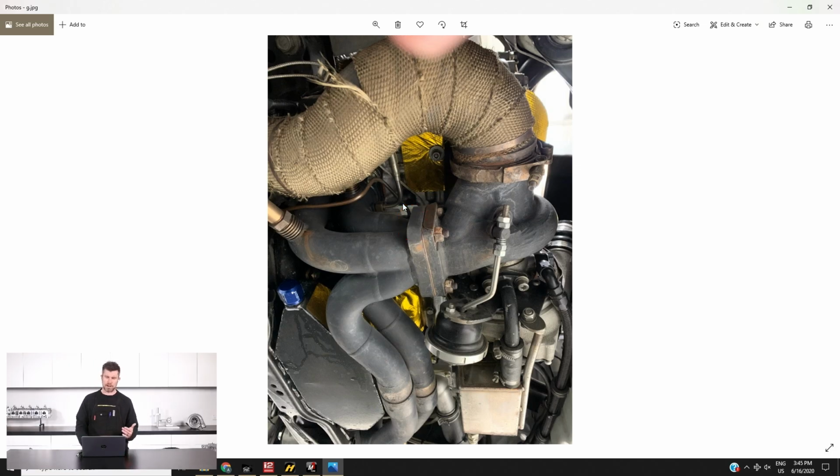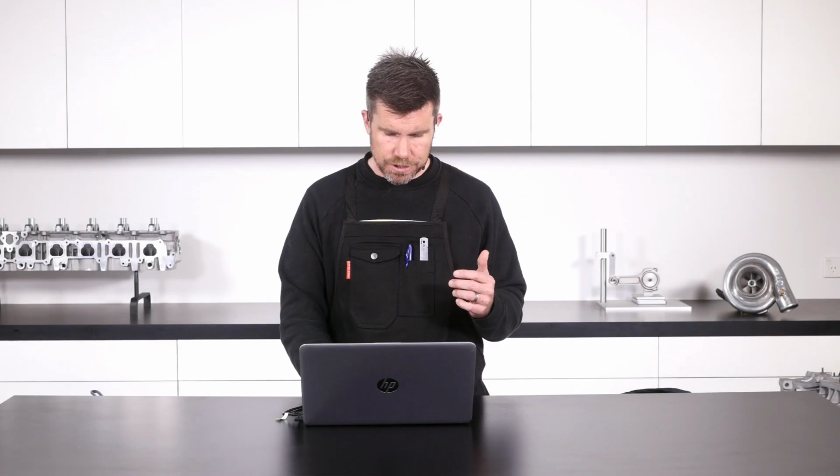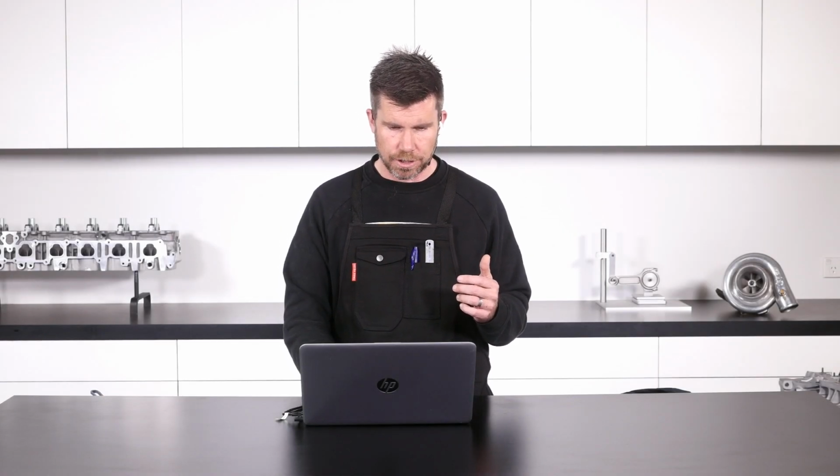And with this one here, I've ended up with probably somewhere between about 3 and 4 feet of length in that copper tube, because it runs all the way down to the back of the engine along that front pipe, and then it actually ducts its way up to the back of the starter motor. So again, plenty of room to get rid of all of the heat from the exhaust gas before it makes its way into the sensor. Now I'll just jump across here and show you in a bit more detail.